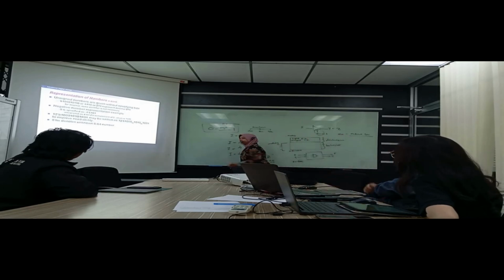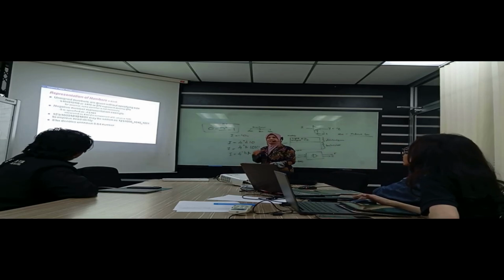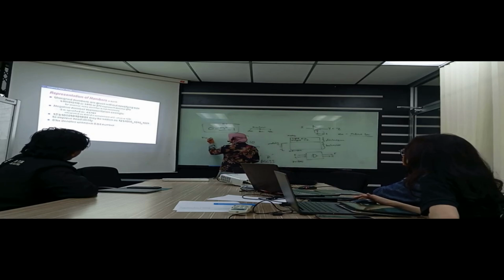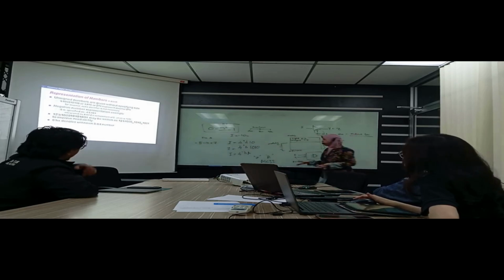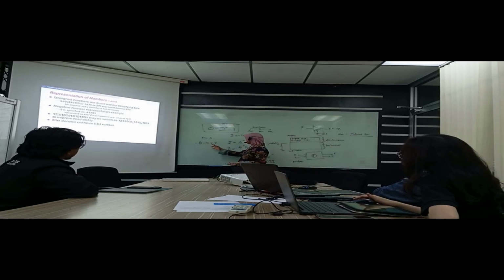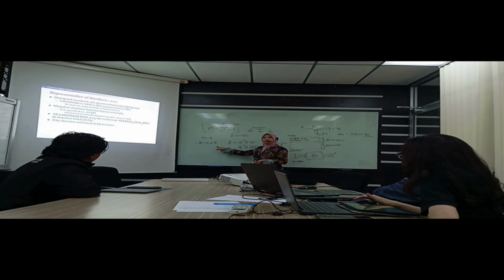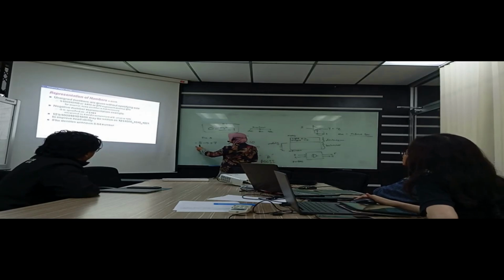The easier way, what I did, is I remember for 4 bits. If n equals 4 bits, the range must be negative 8 to positive 7. I just remember this way, and after that I can play around. Negative 10 cannot be here, so I need to try n equal to 5. From here I can come up with the range.